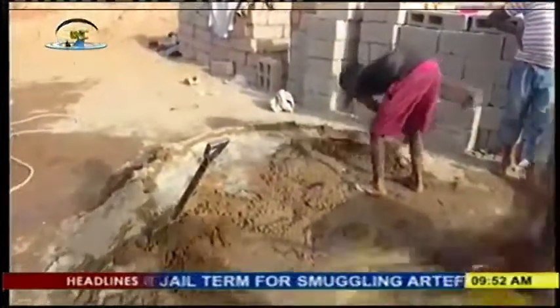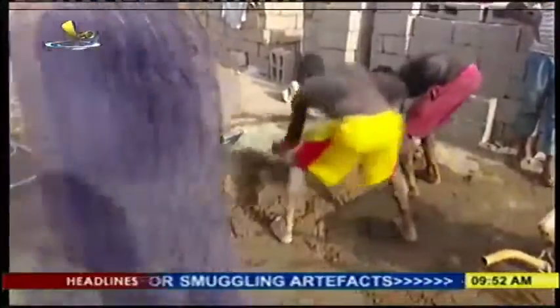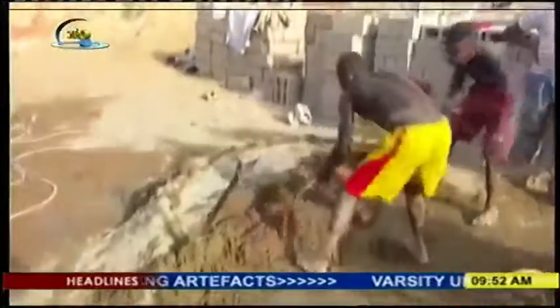I'll give you an analogy. If you add too much water, that means water don't pass Gary. If you don't add enough water, Gary don't pass water. So you have to have the right amount of water in the cement or in the concrete mix for hydration to be complete. If you add too much, once you pass that point, the strength of the concrete starts to take a nosedive.